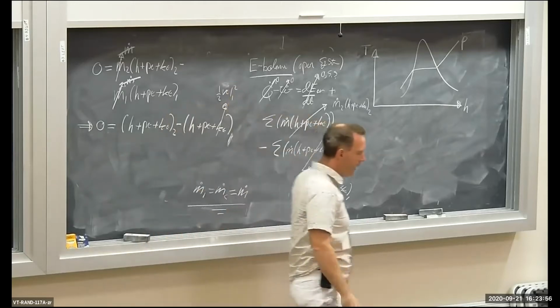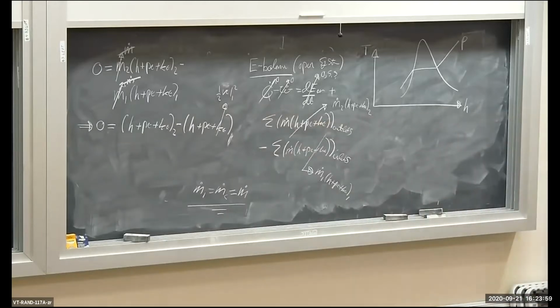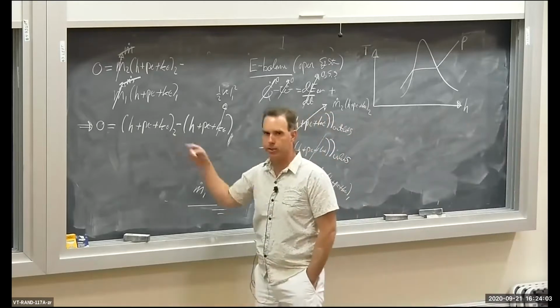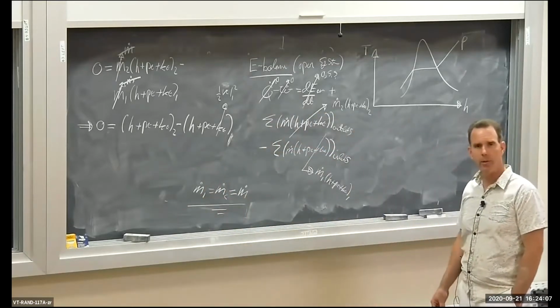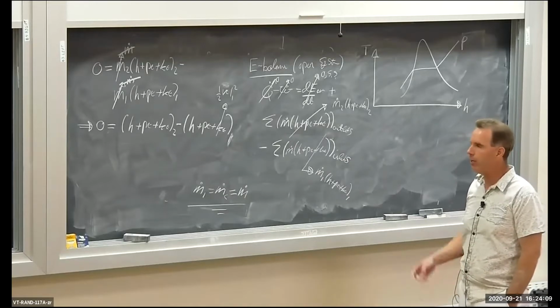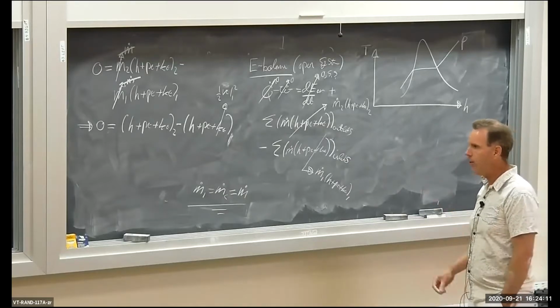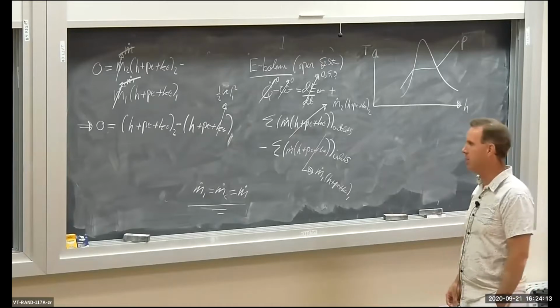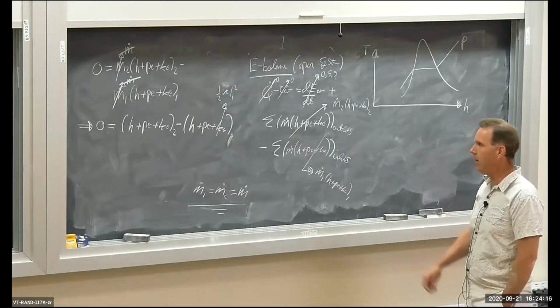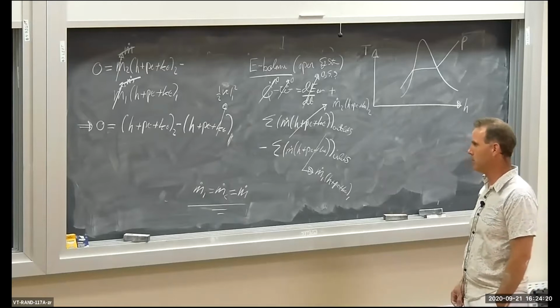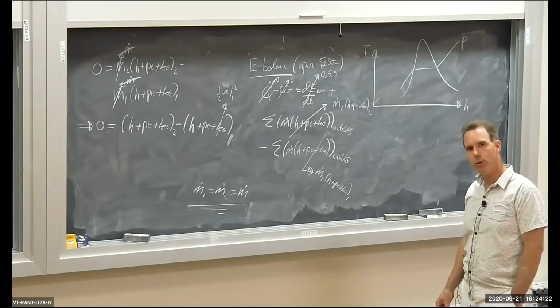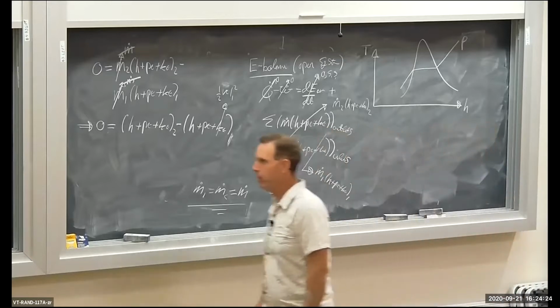And on the outlet, it's going to be 1/2 velocity at the outlet squared. Now, we're not given any information about the inlet and the outlet velocities. I don't have any flow areas. I don't even have any m dots. So I cannot calculate any of these inlet and outlet velocities and therefore specific kinetic energy terms. So I'm going to assume them away.